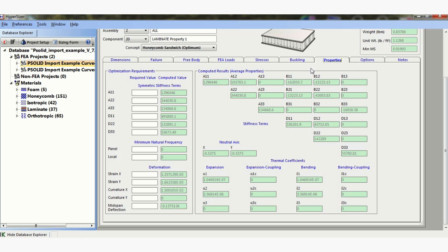You do not want to combine them automatically, then write a margin and not have any clue whether it's thermal that's driving the design. It can be complicated, because the thermal could be adding to the mechanical, it could be taking away. There's all kinds of things going on. So you need to understand the concept of my mechanical load is X and my thermal load is Y, and one is plus and one is minus. And so I'd like to see all of this stuff go on a different sheet. This would make a lot of sense.